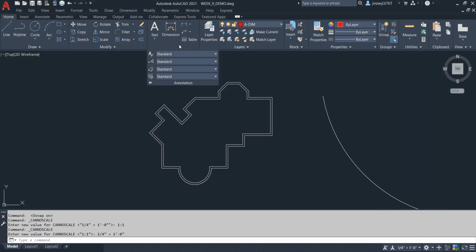Okay. By default, with AutoCAD, if we go to our annotation palette and we drop down our annotation menu at the bottom, you can see we have our text style, our dimension style, the leader style, and table styles. In the dimension styles area, we have our annotative option and we have our standard option. By the preview of these options, I hope that you can tell that they don't really adhere to what we would normally see as an architectural style, right?